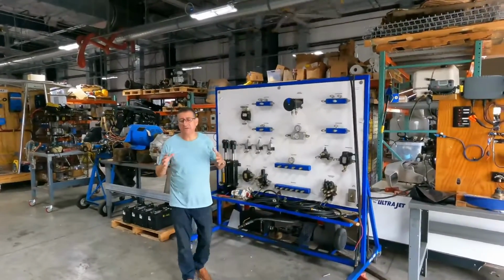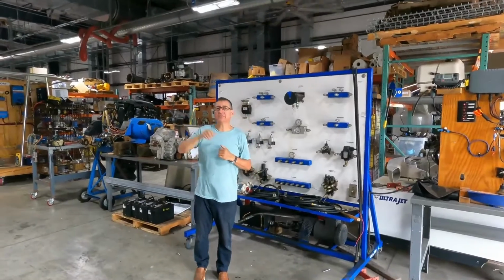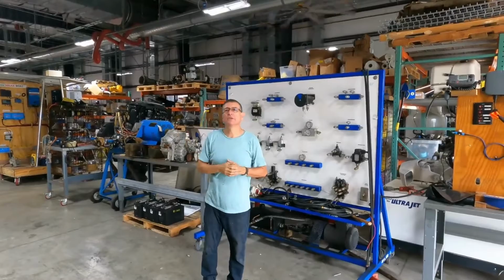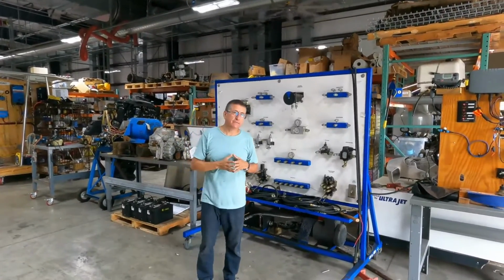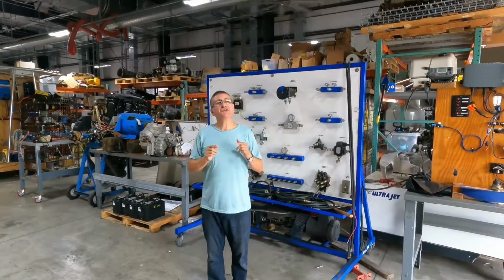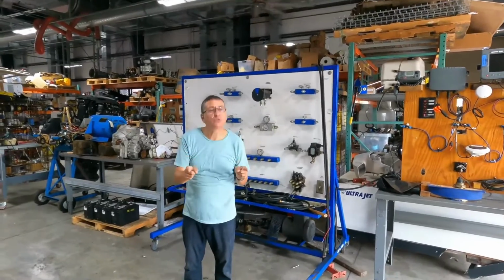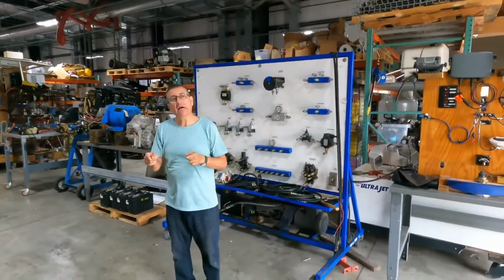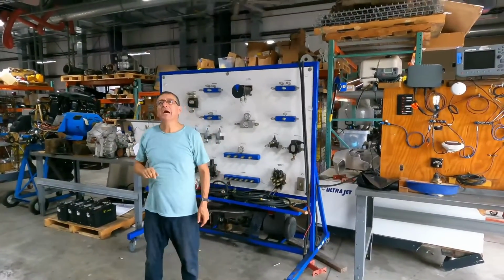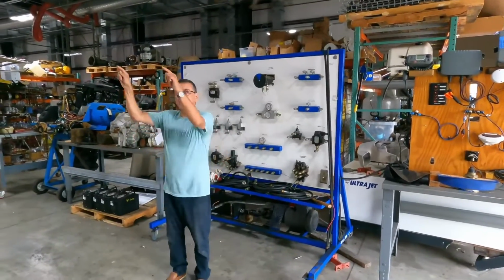This is an example of a central hydraulic unit. For example, in the previous exercise on the board, I mentioned 5 or 6 equipments, no? Suppose that those equipments are hydraulic. I check in each equipment how much flow is required in each actuator, in each motor, and I add the flows in gallons per minute, all of them, and the pressure in each one. And at the end, I create a table.